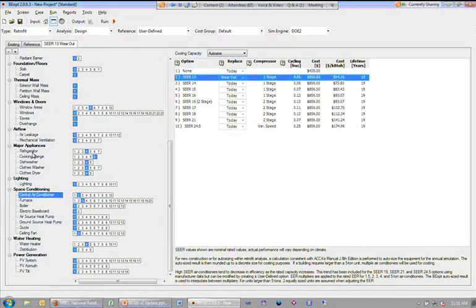So maybe a better example is there may be other equipment or appliances that between years 1 and 10 are getting replaced or improved, and maybe some after year 10. And those improvements that are made after year 10 would not get incorporated in this downsizing calculation because you're going to be putting in the SEER 13 in year 10, and that's when you're going to get your downsizing benefit. Hopefully that's clear.